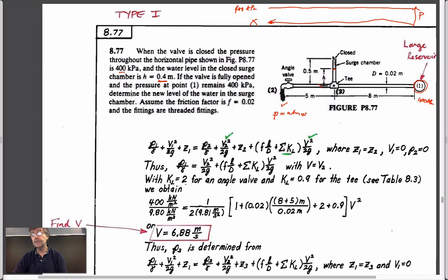There'll be flow in the system which will readjust this limb of water in here, but it won't be flowing, right? It'll readjust as you change the pressure at this point, because now if the pressure here is 0 and the pressure here is 400, there's going to be some change in pressure along here that will be different along these two segments. These will be linear segments. They won't necessarily be a straight line, but the question is, what is this new pressure here at point 3?